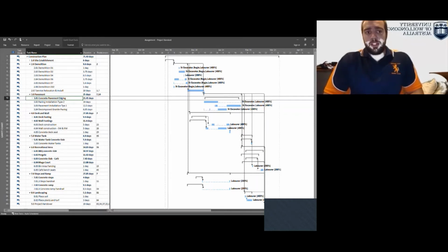We broke the WBS down to a detail that allowed us to account for resourcing to activities that didn't require labour, such as concrete curing. We assumed that our overall resources available to us was a 4-man construction crew with a truck and excavator hire, with the more specific detailed tasks subcontracted out.